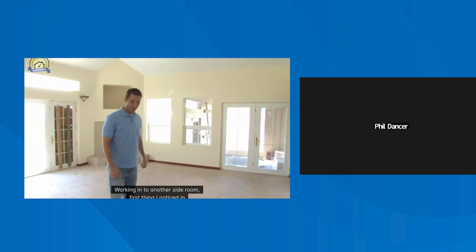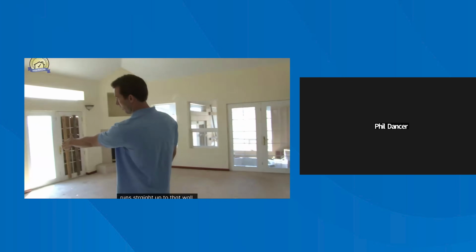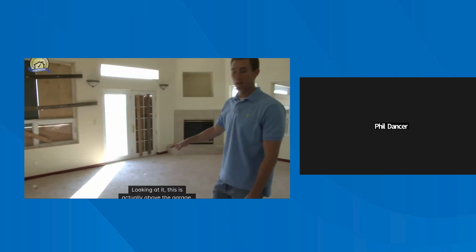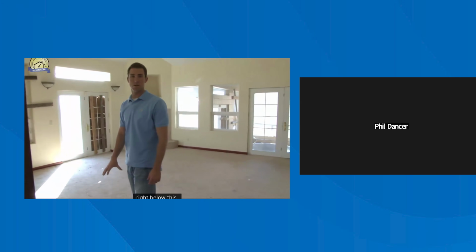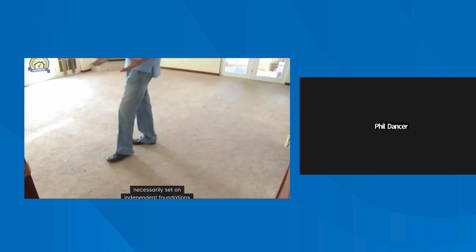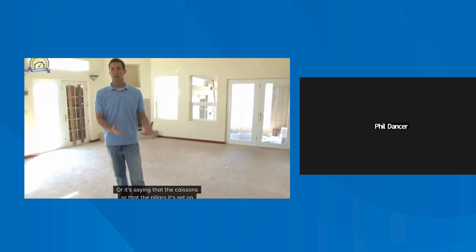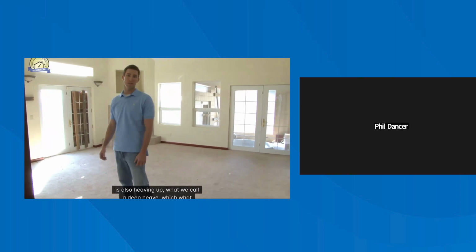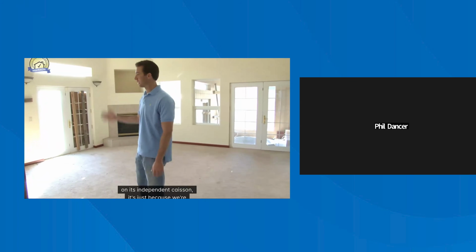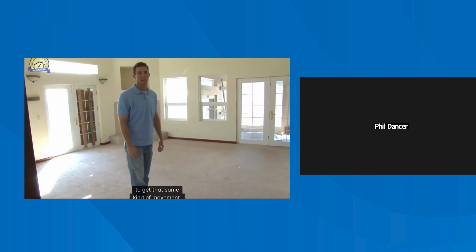Working into another side room, the first thing I notice is a main bulge in the floor, and it almost runs straight up to that wall. You can see along the baseboard where there's a high point. This is above the garage, and there's a main column set in the garage right below this. That's either saying those garage columns were not set on independent foundations and are moving along with the slab movement, or that the caissons the pillar is set on are also heaving up, what we call a deep heave. Given what we're seeing around the perimeter, I would assume it's set on an independent caisson, and because we're getting a lot of vertical movement out of the perimeter caissons, it's not uncommon on an interior caisson to get that same movement.